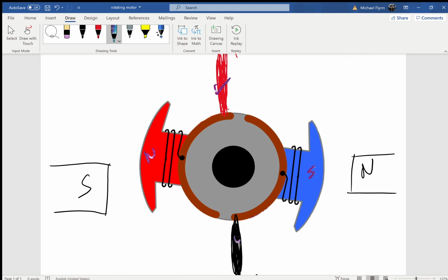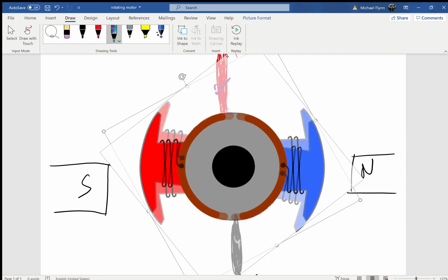But then it would normally stop rotating now, because now that it's sort of reached a point of attraction to this external magnet, but something's about to change. If you look, the red brush is approaching a gap in the split ring, and same with the black brush down here. And in just a moment, they're actually going to pass over the gap, and then the red brush will be touching the other split ring, and the black brush, same thing. But that's actually the whole point. It's really important. Okay, so if you watch, we keep going.